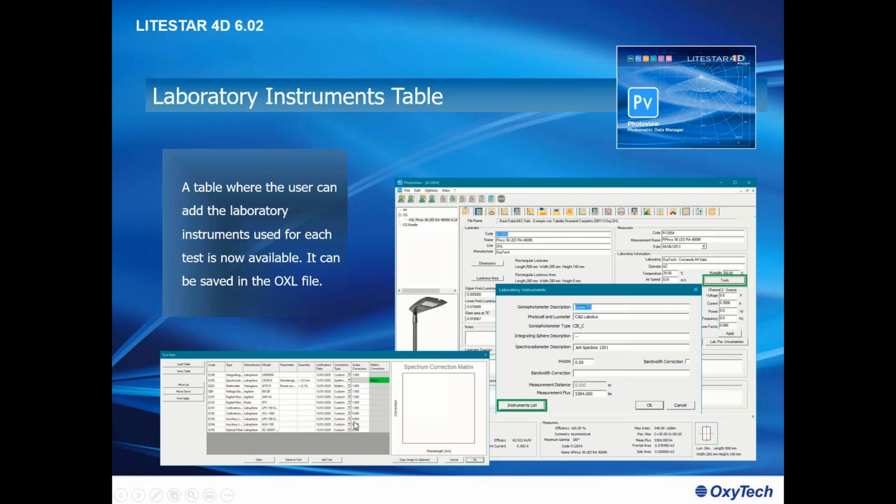So power, current, the tension, in case of electrical parameters, the photometry, or the spectrum in case of photometry and spectrum measurements. And we can come to the instrument table through the Tools button, which opens this window, and at the bottom left you can find Instrument List. Once you confirm, the list will be merged with the information about the luminaires, and then it can be saved again into the Excel file.